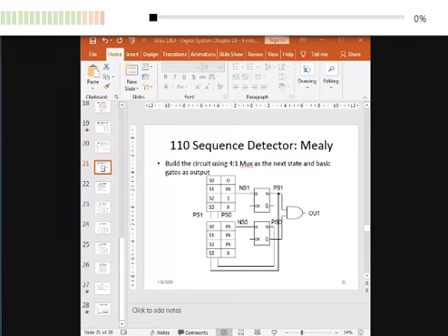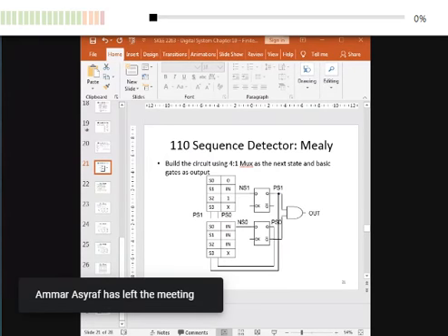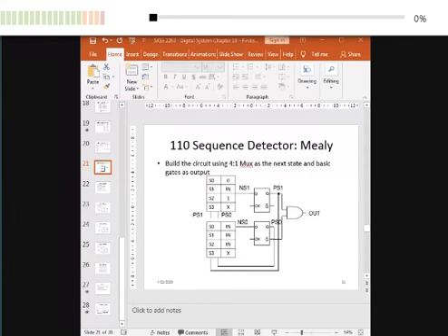Okay. So serial multiplier is a good exercise because even if you build a simple circuit, for example, when I did my master, the filters, I used serial multiplier to multiply the filter. Of course, I need lookup table and so on. But the simplest part in the filter is to do the accumulator, multiply, accumulate, multiply, accumulate, multiply, accumulate. You will learn about filter in digital signal processing class.